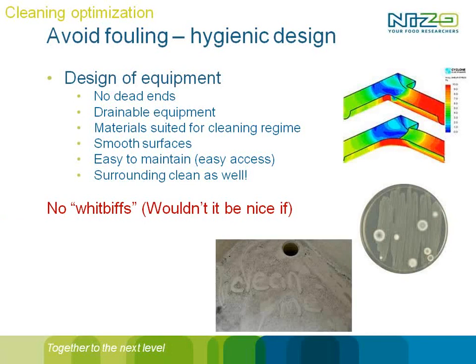Wouldn't it be nice if we add some equipment or add a nice piece of piping somewhere, so that we have the opportunity to do this and that? If it is not necessary, leave it out. Keep the equipment as straightforward as possible. That's the next one: keep it stupid simple, or keep it simple stupid. Keep your equipment easy. If there is a lot of fuzz around it, extra added options, it usually is a recipe for problems in the future.